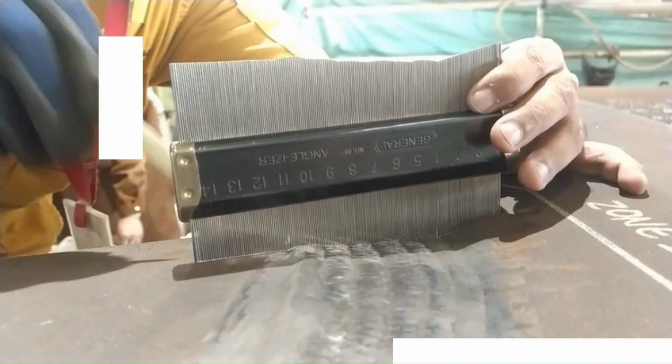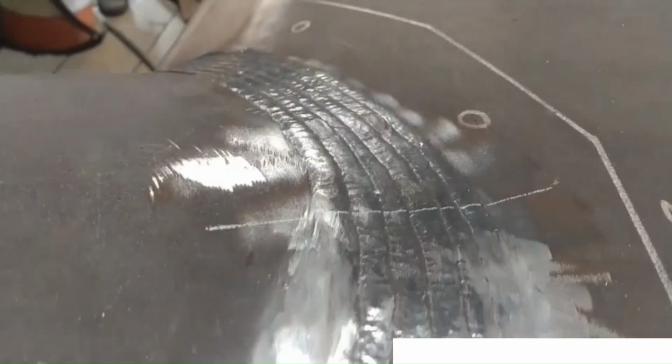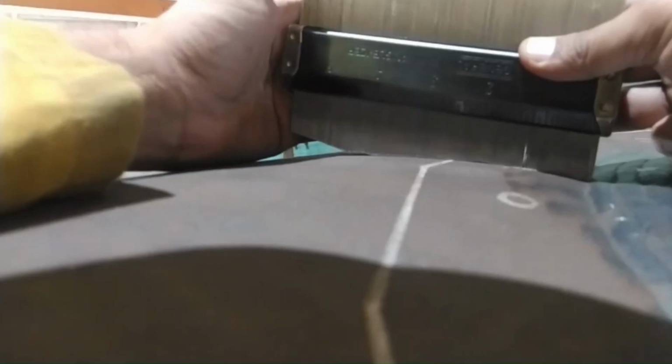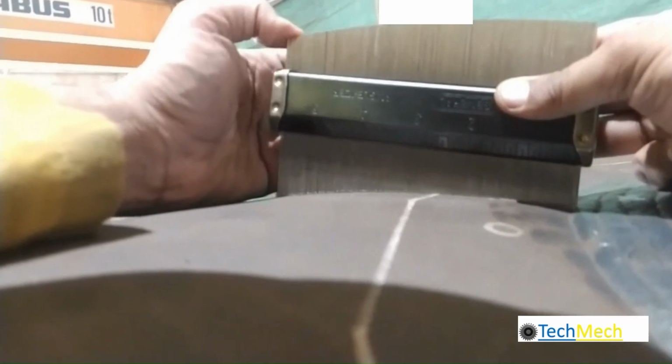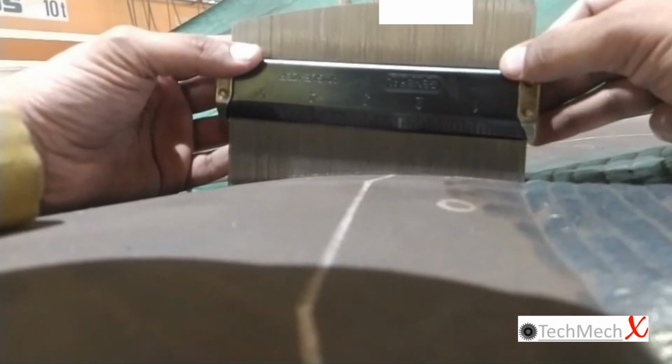Perpendicular to the weld, draw a line where the gauge is placed using marble chalk. Ensure all wires of the mimic gauge are properly set on the weld profile. Draw the profile with a pencil on paper. Then take the profile of the chord curve with the mimic gauge. Transfer and extend the curve of the initially taken profile onto the profile sketch.